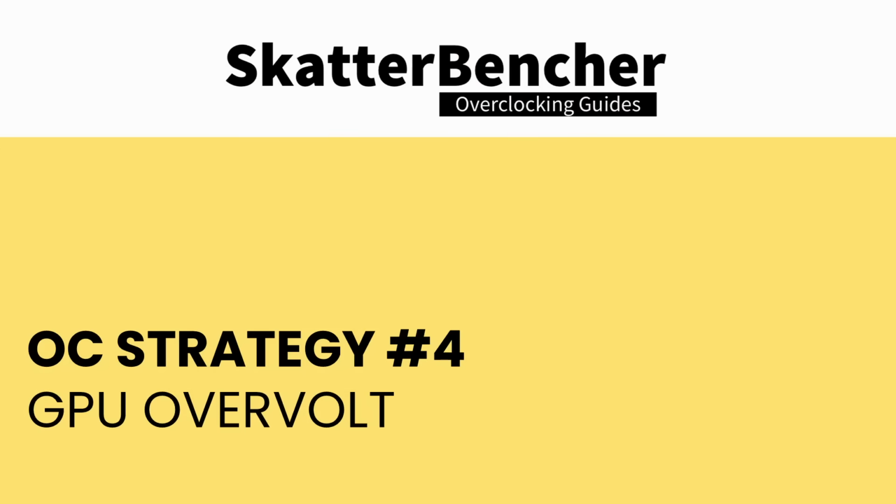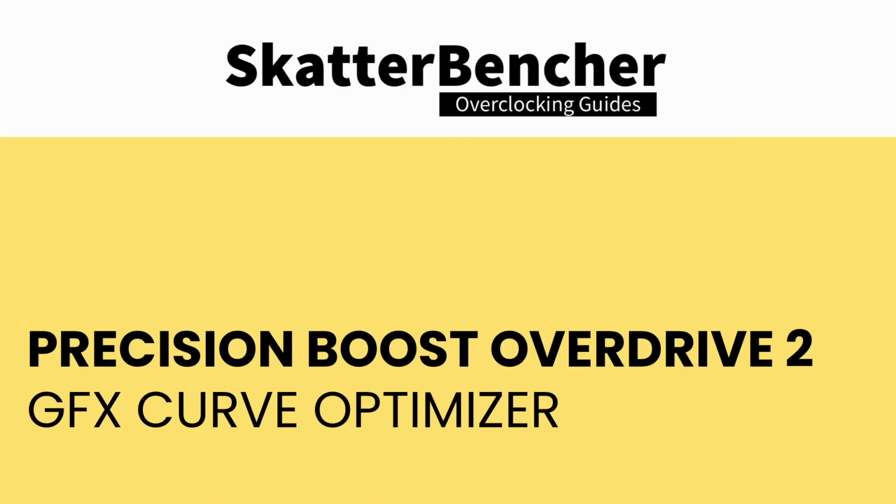In our final overclocking strategy, we do everything we can to squeeze even more frequency out of our GPU, which includes overvolting using the graphics curve optimizer. Curve optimizer is one of the most important tools in a Ryzen overclocker's toolbox. It's most commonly known for its CPU core undervolting capability, but for AMD Ryzen CPUs, it's also available for the integrated graphics. To explain how it works, let's start with the basics, the voltage frequency curve.